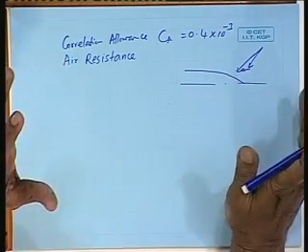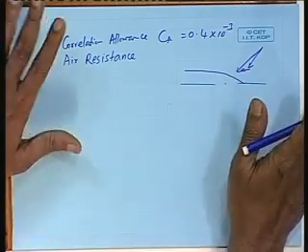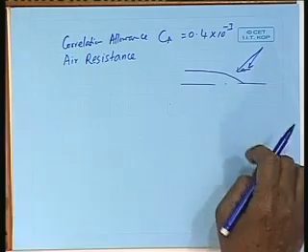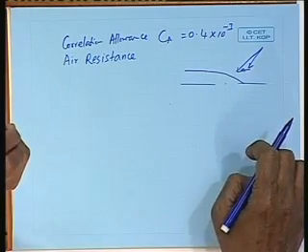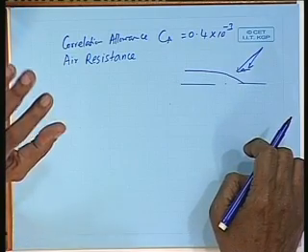You can actually calculate the resultant wind velocity, on the basis of which you will calculate resistance. Clear? Okay. Now, we are mostly interested in the drag to forward motion, so wind coming from front. When wind is coming from front, what is the windage area that it faces?